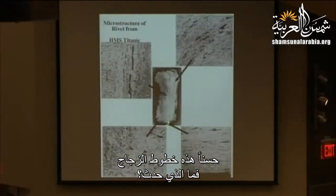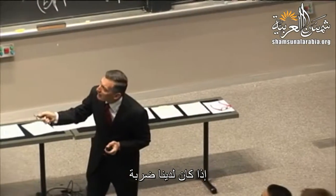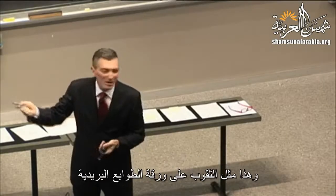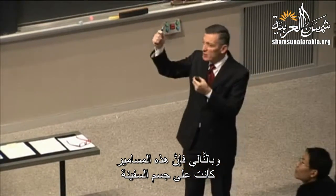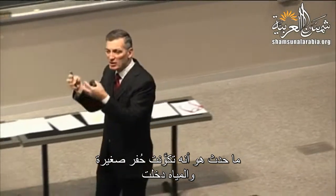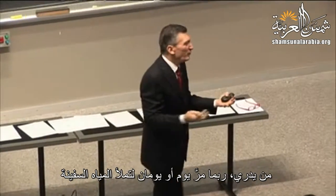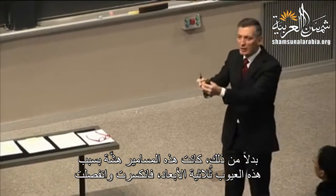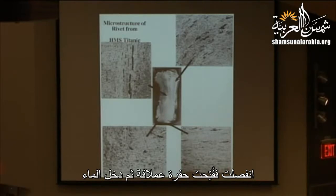So here are the stringers. What do you think the mechanical strength of this is? If you have an impact like so, instead of having the toughness to absorb the impact, these things broke. This is like perforations on a sheet of postage stamps. These rivets were on the hull, and when the ship hit the iceberg, what should have happened is there should have been a small hole. The water would have taken, who knows, a day or two to fill up, and there was plenty of time to get rescue vessels. Instead, these rivets were brittle, thanks to this, and they just unzipped, pop, pop, pop, pop, pop, opened up a giant hole, and then took on the water.